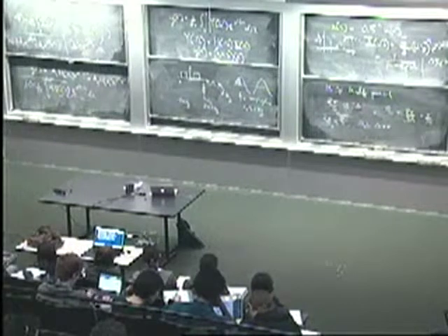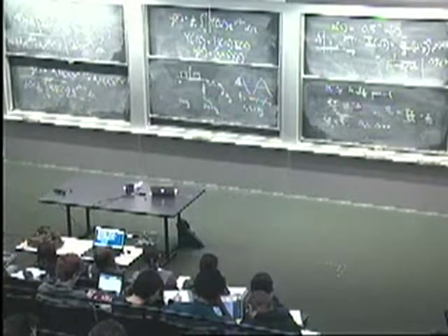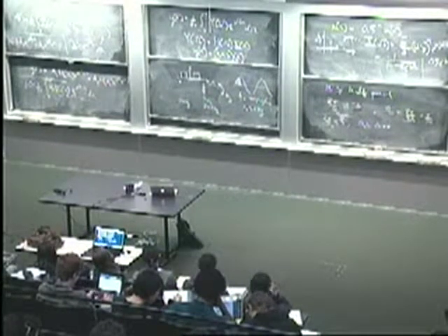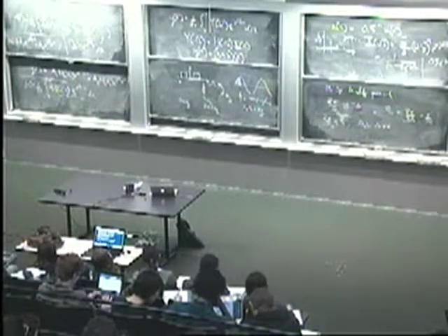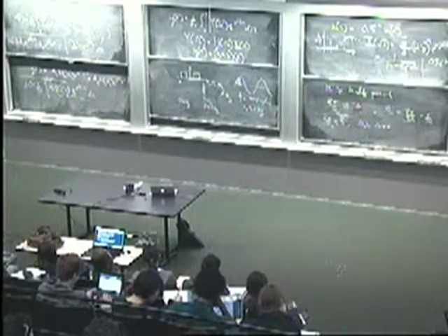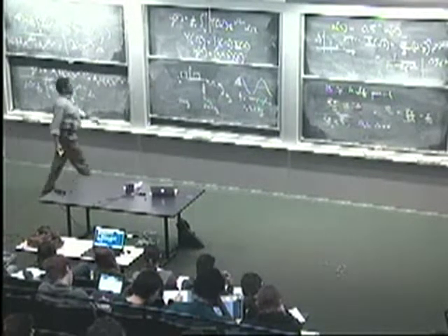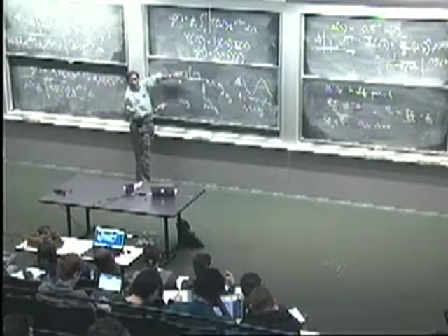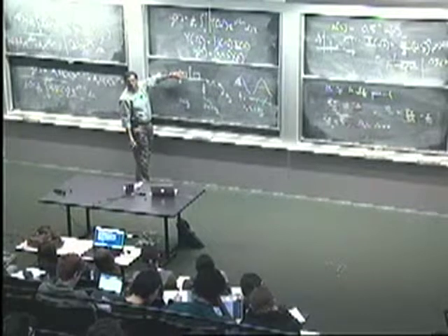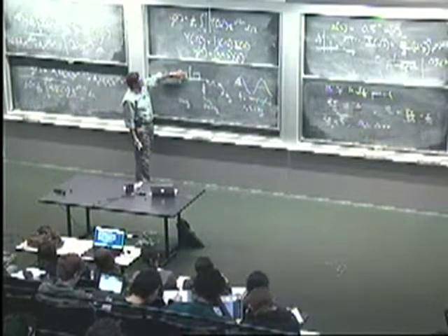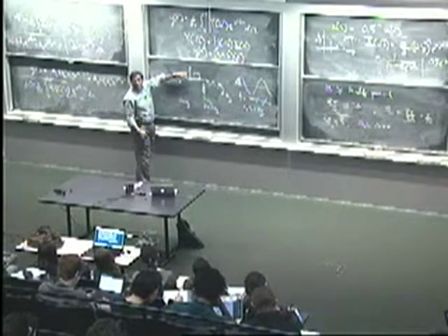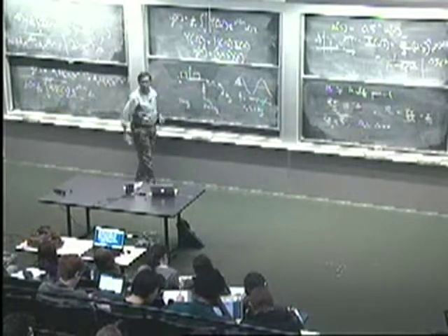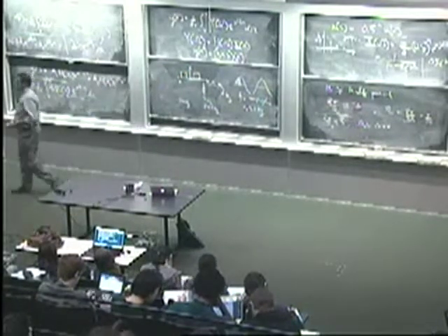So when you're trying to visualize what this characteristic is telling you about what you're seeing with a discrete time sequence, that's really the mapping. The other thing about these characteristics is that people only plot the positive frequency part. So they ignore the negative frequency because of the symmetries there. Okay, so in applications, when they give you a frequency response, they will typically just give you the positive frequency part of that.